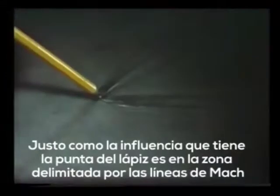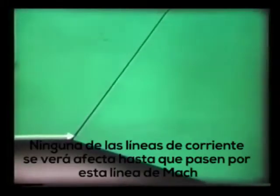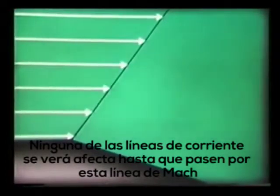Consider a streamline very close to the surface. The influence of the sharp corner will be felt along a Mach line at the appropriate Mach angle, just as the influence of the pencil point is confined to the region bounded by the Mach lines. None of the streamlines will be affected until they reach this Mach line.